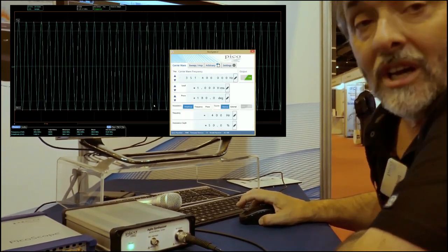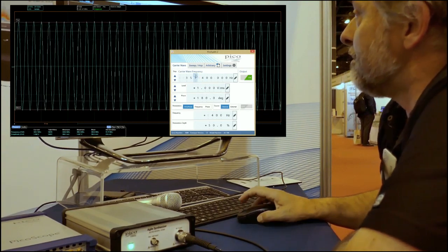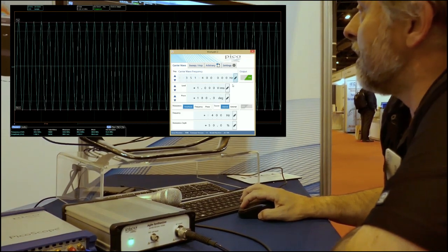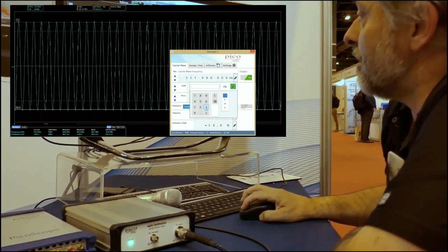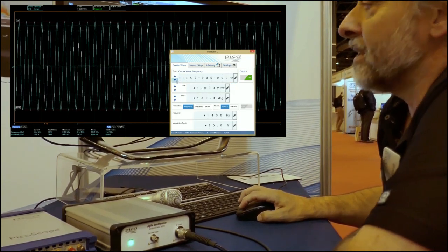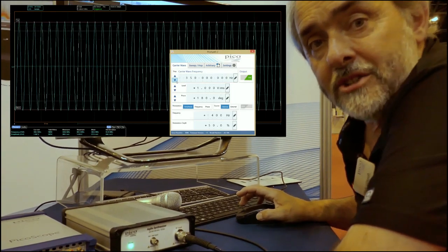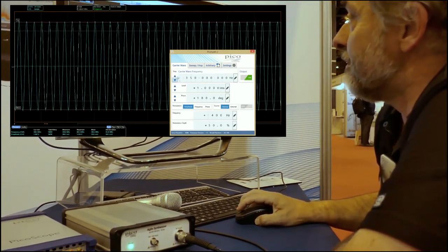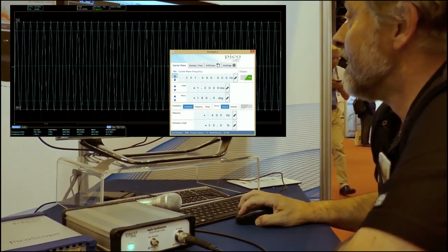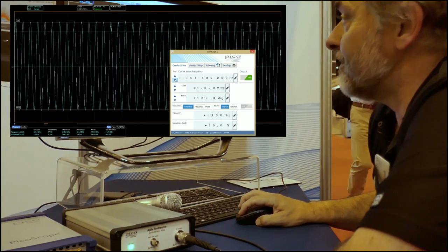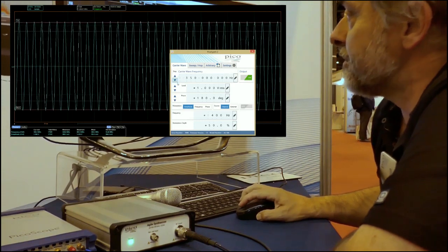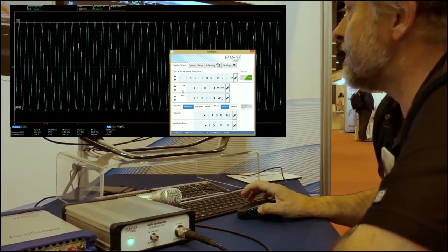So here's my carrier wave screen. If I just show you around here, we've got increment and decrement of frequency. We've got the ability to type in frequency. We've got the ability to set a custom step size for any of the parameters. In fact, step size here is about 13 megahertz that I set up earlier, and we can just step through the custom settings there. So you can see I've got basic controls for step, level and phase.